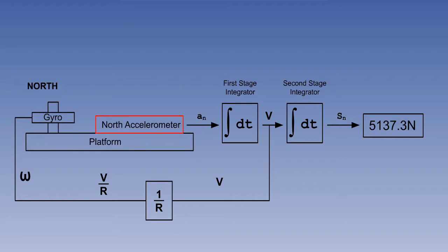Accelerometer bias is next. The accelerometers are designed to give 0 output for 0 input, if properly leveled. However, due to manufacturing imperfections, there may be some slight output when the accelerometer is perfectly stationary and level. This is called accelerometer bias. Next, we'll look at integrator error.